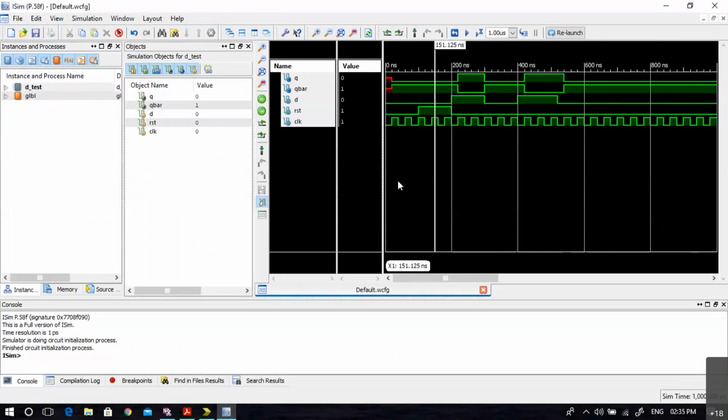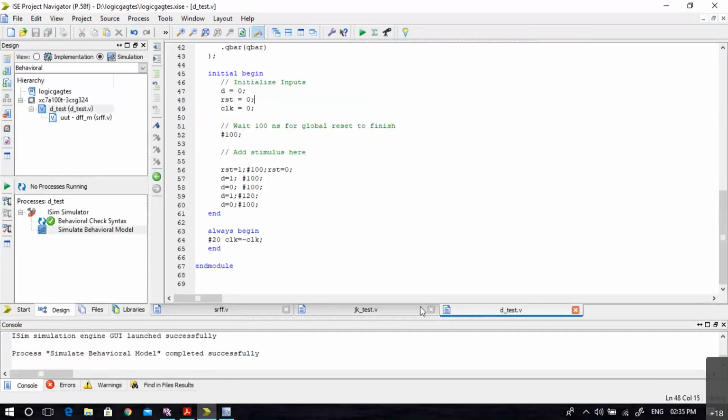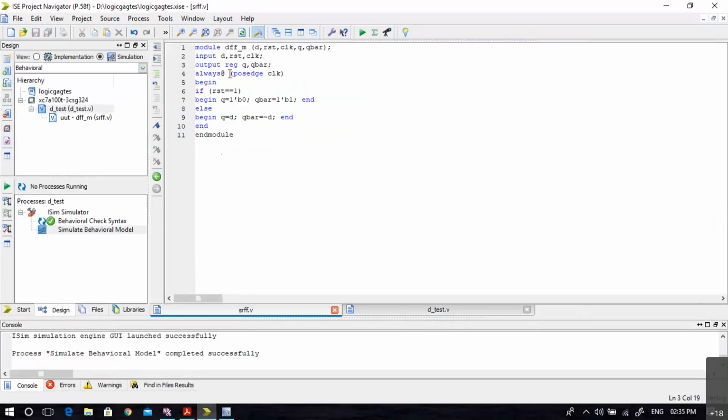So now you can see initially when reset is 0, output is in red color, unknown. Later on, from the rising edge of the clock. Why has this happened here? Because in the code you can see always at posedge clock is there. Which means now reset became synchronous. This particular D flip-flop is now having reset as a synchronous input. This code refers that way. If you don't want this, then you should give posedge clock comma reset. Right now, as we have given only posedge clock, we have not given the reset in the sensitivity list. That is why output is coming this way.